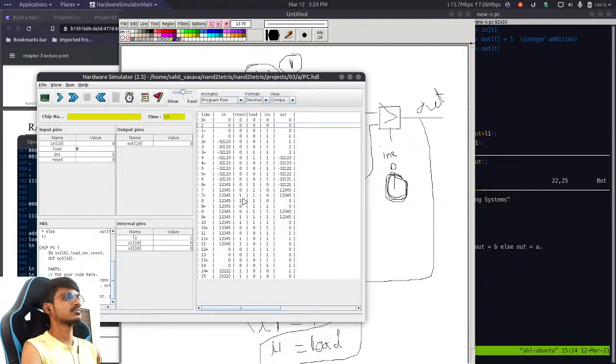Great. And the reset bit overrides all these two variables. So on the 7 plus 1 clock cycle, if we pass the reset bit as 1, then on the 8th clock cycle we will set this value as 0, and on the 8 plus 1, if we pass 1 1, then for the 9th we will load the value.